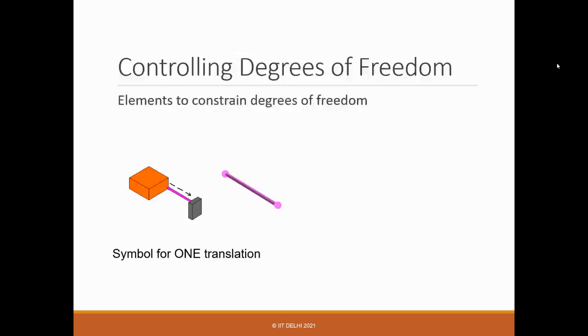If we take a simple bar or a link, articulated along the constraint line, that will impose one translation constraint. So in this case, if we have this pin, or call it a link, and it is articulating, all the motions are possible, right? This is the link we are talking about. When we talk about this articulation, it means it can rotate. The only thing it will not do is move along the translation direction. This is the constraint.